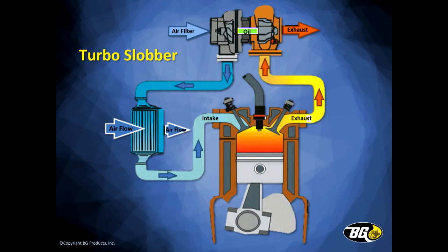Oil lubricates that shaft. And if you're not maintaining these systems properly, and that seal starts to go because the bearings are worn out, oil will leak out of that turbo and go in through the intercooler and be sucked into the intake manifold. My question to you is, will 109 fix that? No. So be mindful of that.